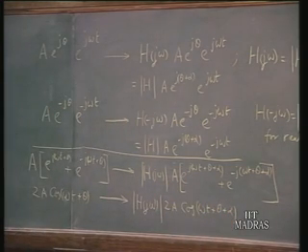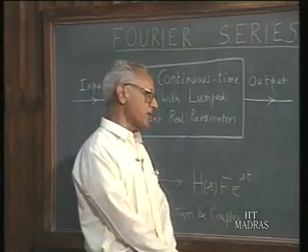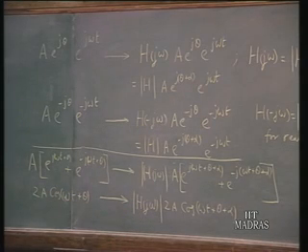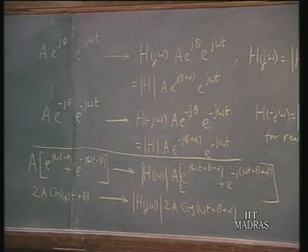So what do we have? We have a sinusoidal function of time with an amplitude 2A. The output is also a sinusoidal function, but the output is modified in magnitude by this factor, the magnitude of the H of s, which we call the system function, as you recall. Phase is also modified by an angle α. That α is the angle of H of jω.